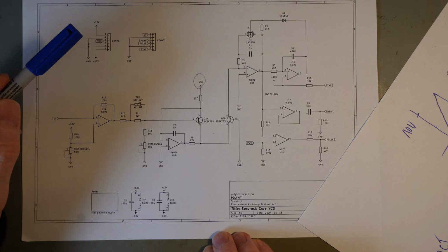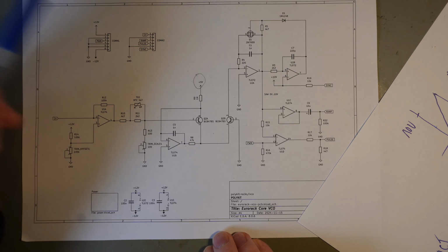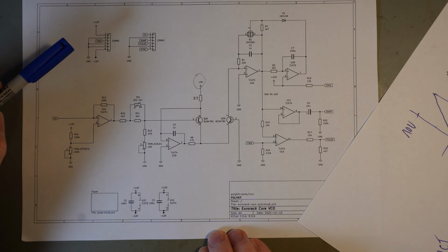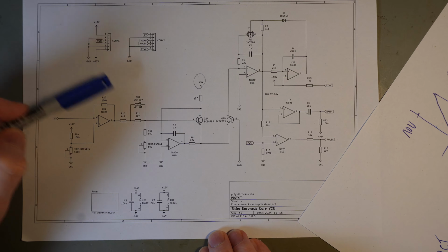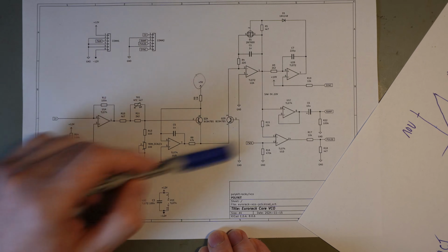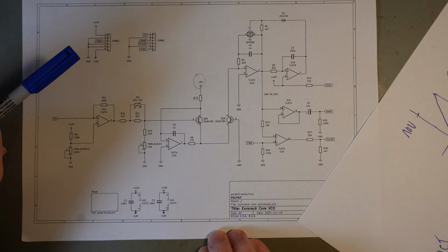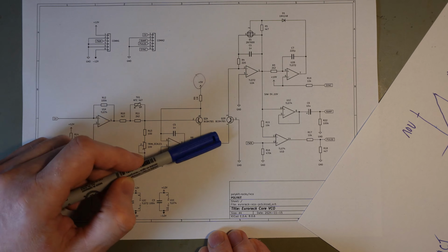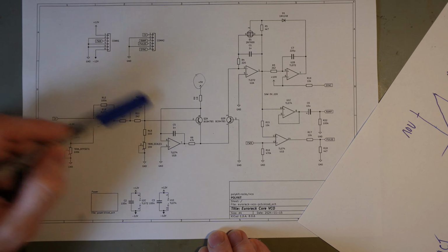So this is why they succeeded in the end to digitally controlled oscillators like DCOs, or even fully digital oscillators like wavetable oscillators and so on. So to complete this here, I already talked about temperature issues. So temperature changes will change the properties here of the exponential current sink, and so this is why a good matching is important. And you also see here a thermistor.